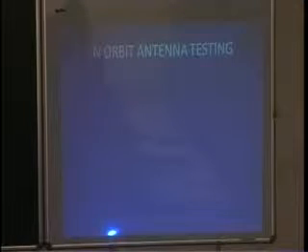We again take all the cuts by moving the satellite in space. We rotate the satellite in pitch and roll for limited angles, say 5 or 6 degrees. We rotate it using the fuel of the spacecraft, and from the ground station we are able to take the pattern measurement. Once we get all the amplitude and phase, or the co and cross polarization signal, then we say yes, it's working.